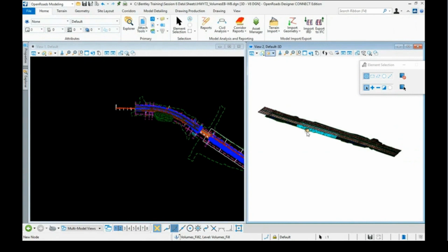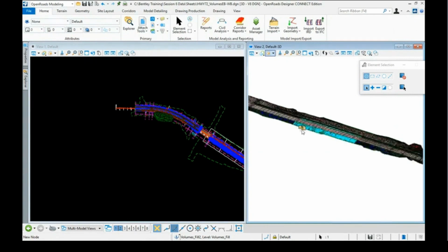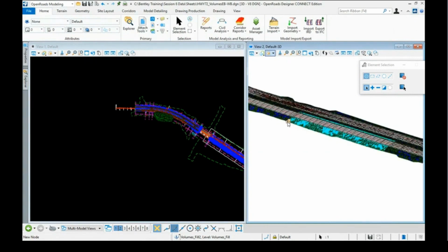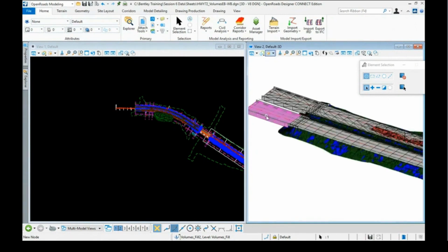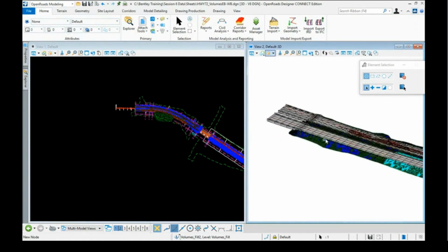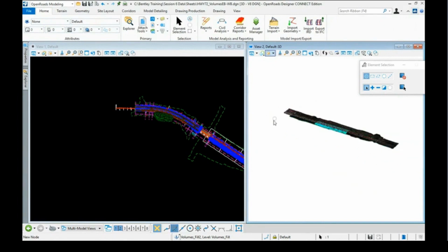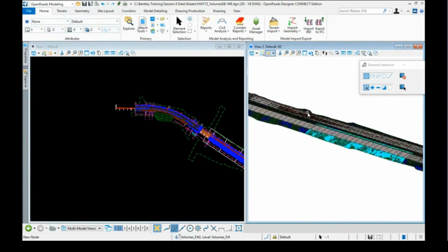And you'll also notice that it didn't just clip and write into the file the cut and fill graphics there. It actually, again, took everything that had a feature definition on it. So it got part of my bridge here. It's taken my bridge elements and added those in. The lines for shoulder, if we had guardrail, it would copy that in and it would show the length of the guardrail, and it would show it clipped every 500 feet or every interval that I defined back in my drawing boundary. So that's a very powerful tool in and of itself.